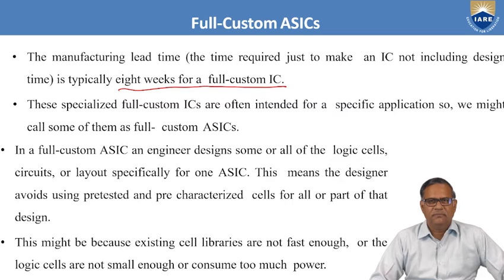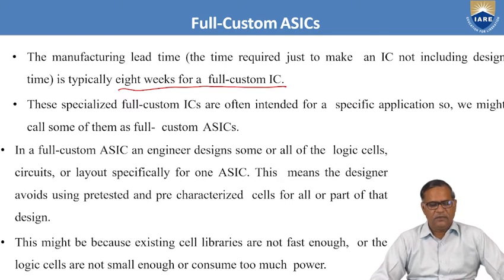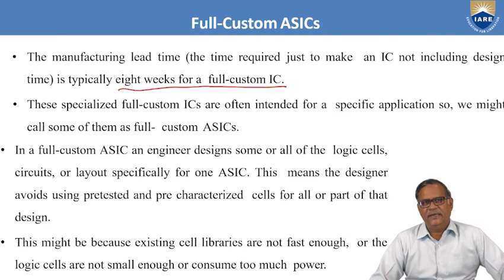In a full custom ASIC, the designer designs some or all of the logic cell circuits and layouts specifically. This means the designer avoids copying from other standard libraries. He avoids using pre-tested, pre-characterized, or proven cells for all or part of the design. He doesn't believe in libraries from other places.